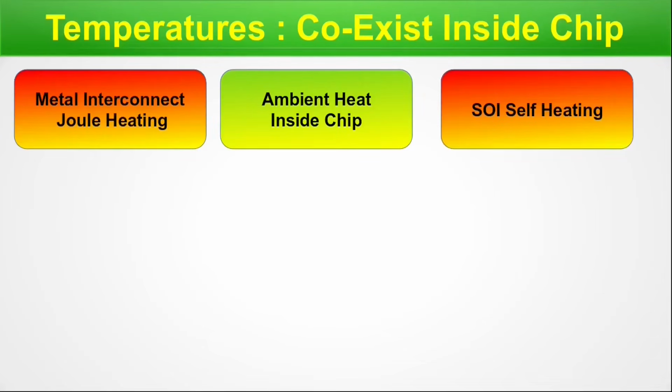Next is the SOI self-heating. You must know that UT-SOI CMOS are nowadays very popular because of the low leakage factor. However, SOI increases the self-heating. It's a huge effect, and I think in many simulators, this self-heating effect is nowadays also getting considered for EM. And one more thing, the FinFET and gate-all-around devices, some of them are bulk. However, many of them are SOI devices. Whether it is basic CMOS, or FinFET, or gate-all-around, the SOI impact of self-heating is there. Nowadays, we also consider the self-heating effect for the EM violation.